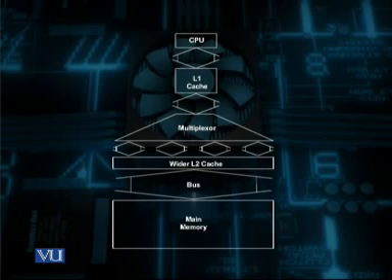The CPU to level 1 cache bus is 1 word wide, and the level 2 to main memory bus is 4 words wide. And a multiplexer is used to interface the wider L2 cache with the narrower L1 cache. In order to see how the performance of the CPU is improved and what is the impact of this design on the bandwidth of the memory.